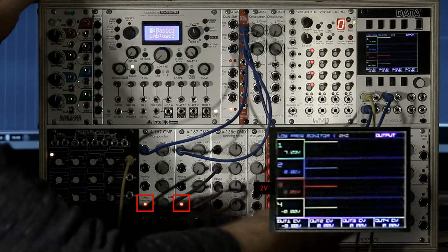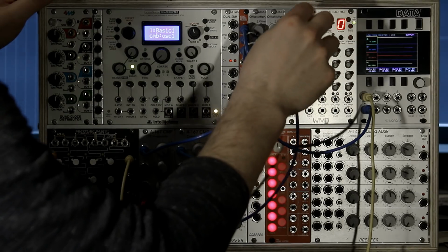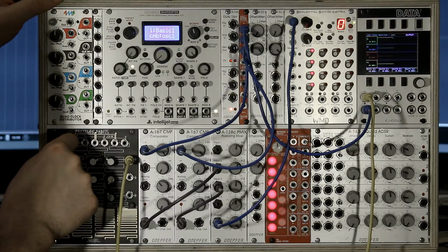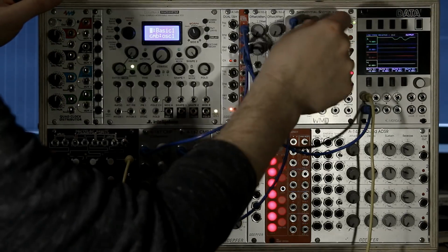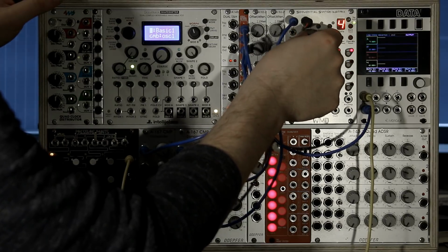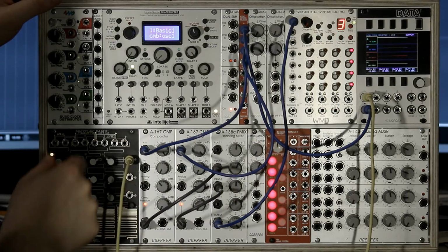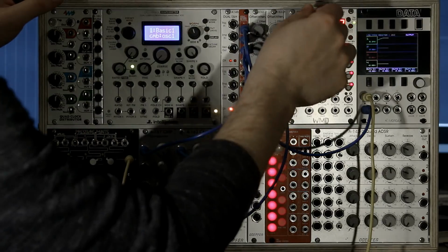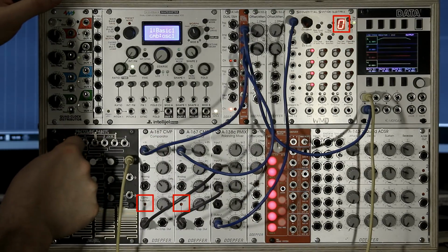We can now use the mixer output as control voltage for a sequential switch matrix. Any switch with CV controllable output selection can be used. Changing the main voltage changes between 3 different sequential switch matrices. I will attenuate the CV input a bit more to make it use the first 3 matrices only, and that would be index 0, 1 and 2. You can also see that the comparator LEDs light up in sync with the matrix selection change.